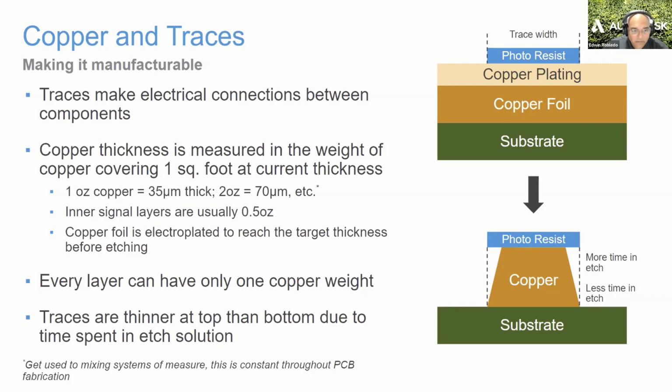And this is some information that you need to provide the board house, because the application itself, when you generate or export the files, doesn't really carry that information. So you should really let the board house know what thickness you wish to use. Yeah, that's a great point. One of the common file formats you're going to use to transmit the board fabrication information is the Gerber file format, and that's literally a direct light plotter control. There's nothing additional on top of that.